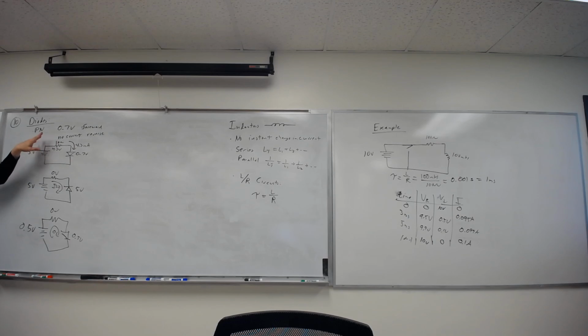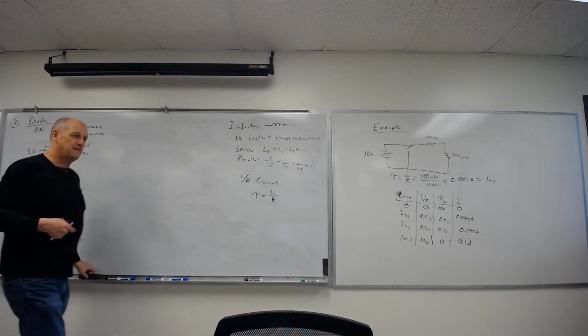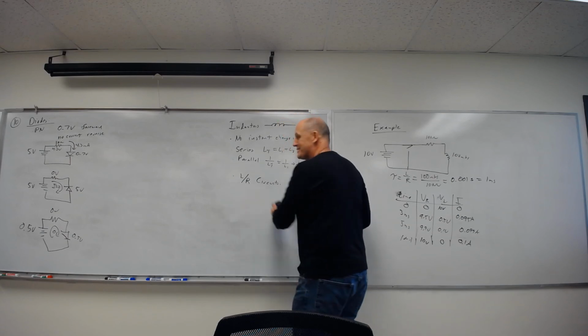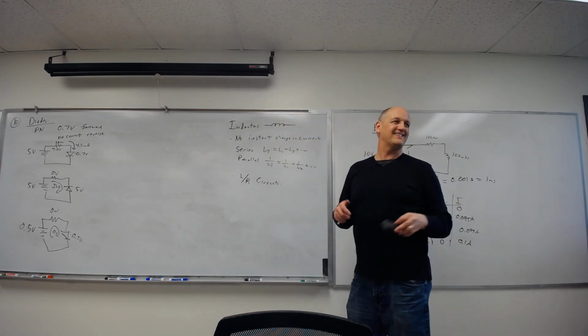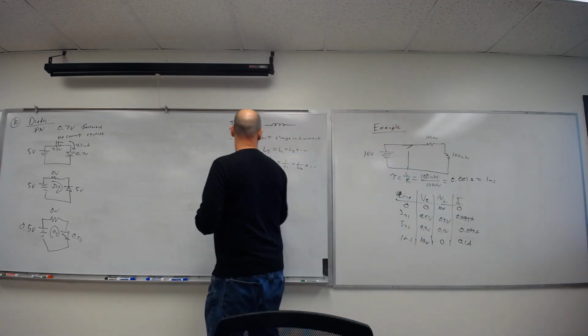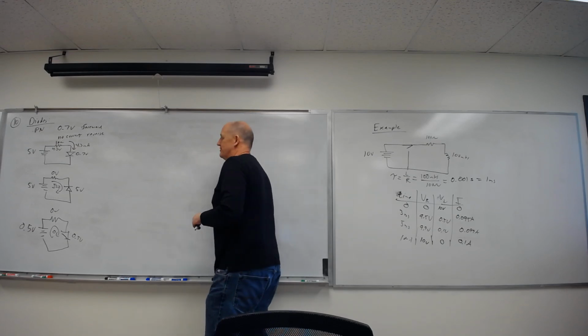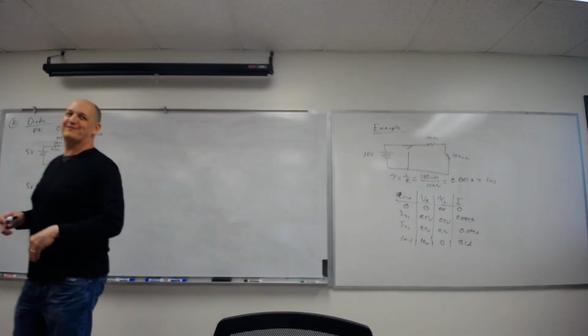Okay, so just watch these in case, because like I said, a lot of times I'll give you an LED instead of a p-n junction, and then I'll give you the forward bias. Use the forward bias. If I say it's 2 volts forward, then you make that 2 volts, and that's only 3 volts. If it's germanium, I'll tell you 0.2 volts. Those don't come up very often, but it is mostly an audio thing. People pay ridiculous money for new old stock germanium diodes from 1966 or something.